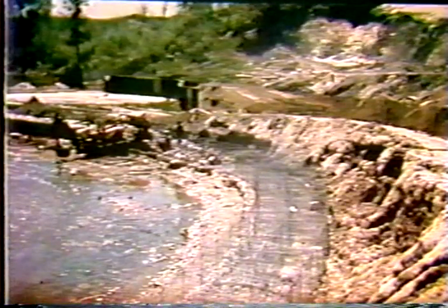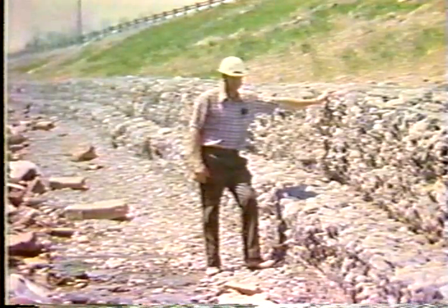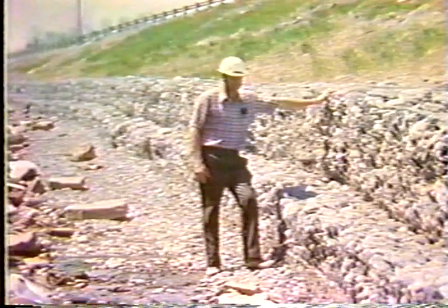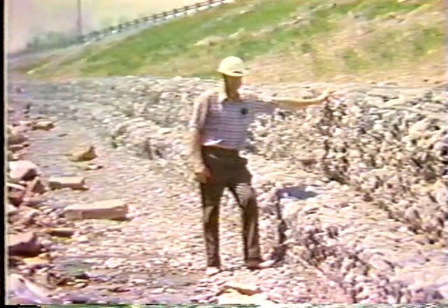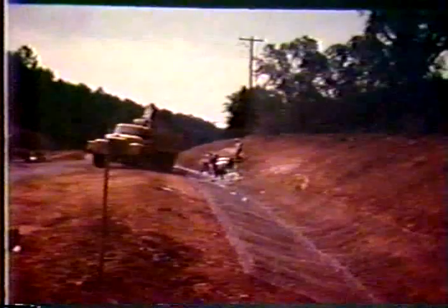This particular slide just shows the placement of gabions at a particular location. You see they've assembled the things. Like I say, those could have been pre-assembled in small segments and brought out to the site and then put in place. They could be assembled in the maintenance yard. In this particular slide, this is a good application of a gabion. You've got perhaps a stream, or a dry bed stream, you might say, but it's used to protect the toe of a large slope. Very good application. It holds things in place.